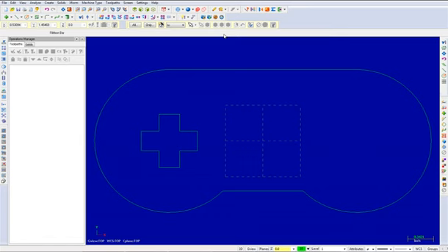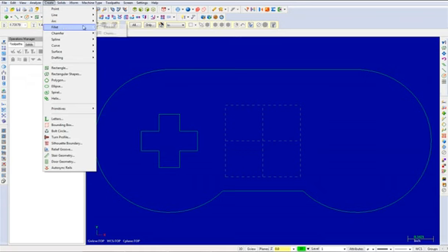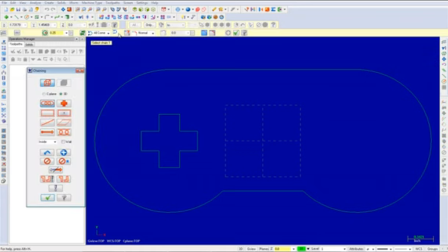The next thing that we will do is fillet chain. In this step, we will fillet all the sharp edges of the shape using the Fillet Chain command. Select Create, Fillet, Chains. Leave the Chain button enabled in the Chaining dialog box. Select the following chain as shown. You can now select the OK button to exit the Chaining dialog box.